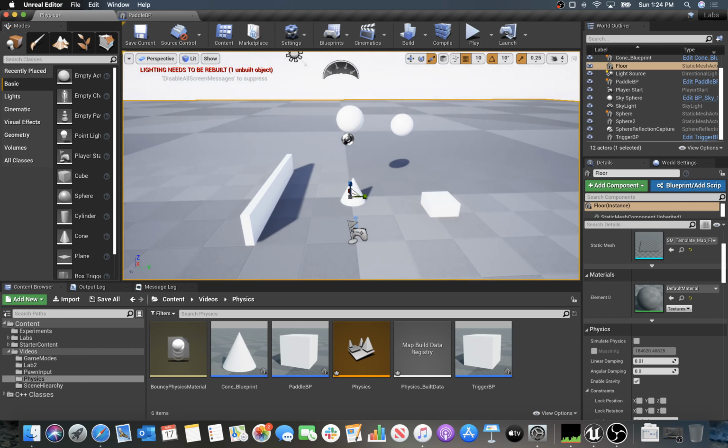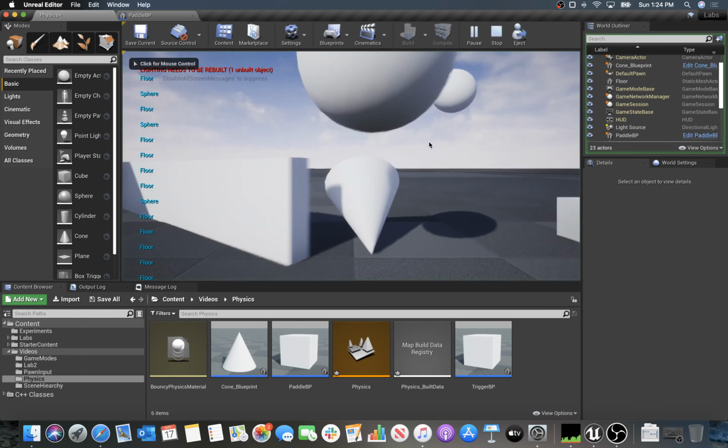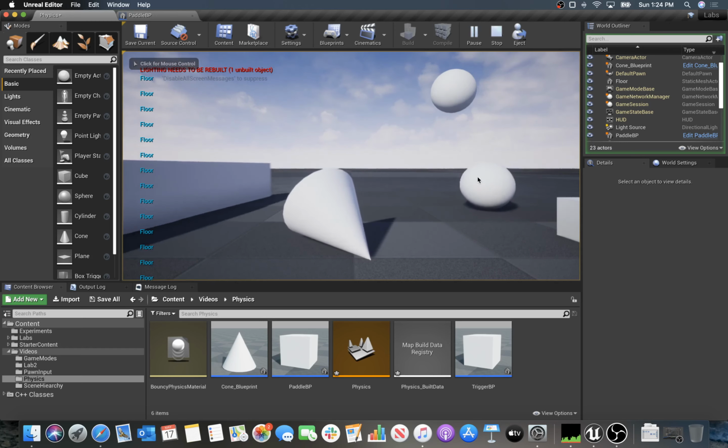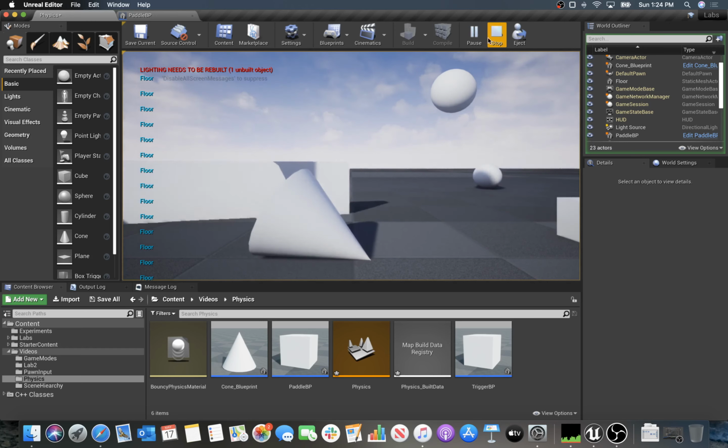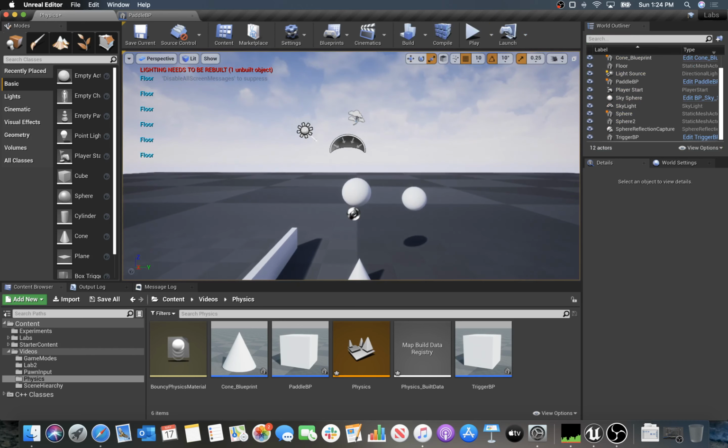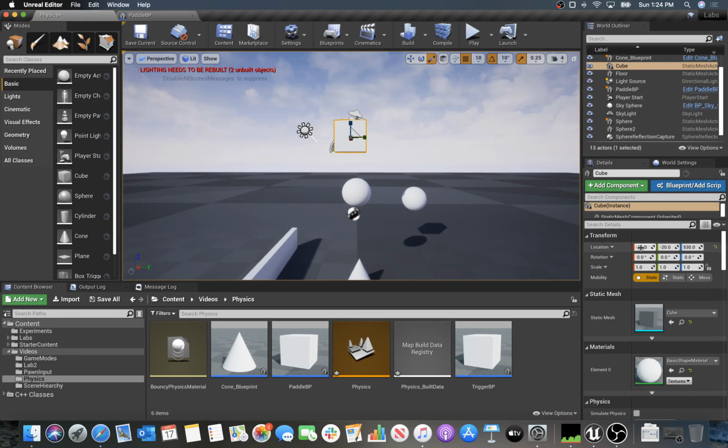The next thing I want to do is, when we had our system set up before, we have this spinning sort of object that's hitting a cone, or missing the cone, but hitting the sphere. Instead, I'm going to constrain this first sphere to a cube. And the way I'm going to do that is by taking a cube and I'm going to place it into my scene. Then I'm going to set the cube's location so that it's centered over the sphere, because I know the sphere had a 0, 0 X and Y location on the plane. And this will then serve as the sort of anchor point for the joint that I'm going to connect to the sphere. For this example, I'm going to go ahead and just use a component.